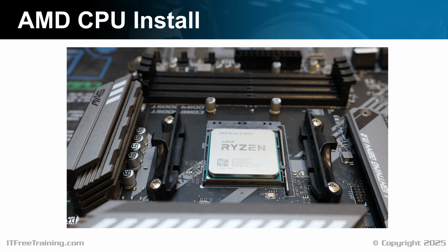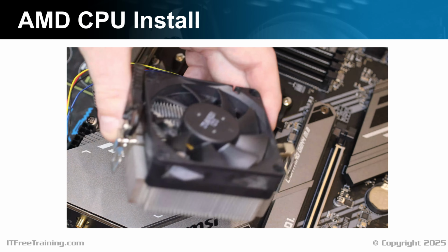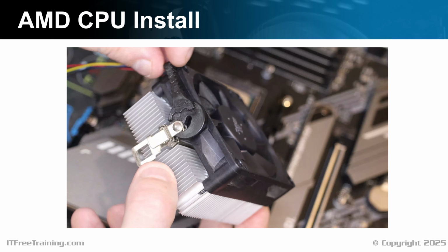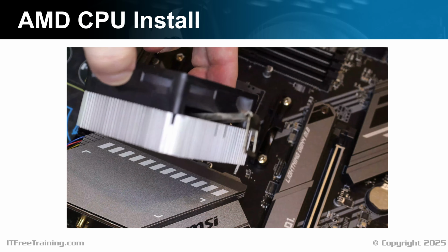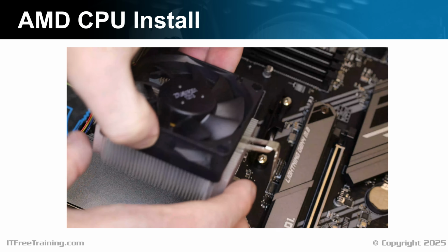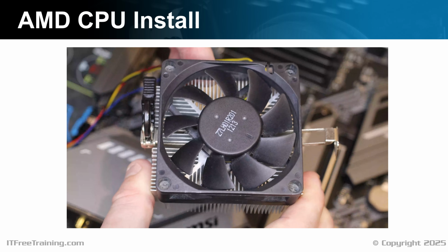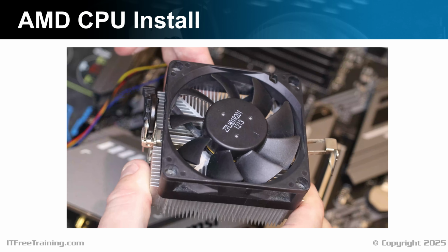The motherboard features 2 retention hooks meant to secure specific types of CPU coolers, typically older models. My older cooler has corresponding hooks that clamp onto these, but it's not suitable for efficiently cooling the CPU as it generates more heat than this CPU cooler is rated to handle. Therefore, I'll use it solely in this demonstration for visual clarity of the installation process. For real-world use, however, I recommend a CPU cooler rated high enough for the CPU you're using.